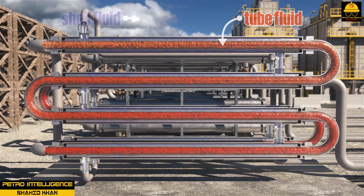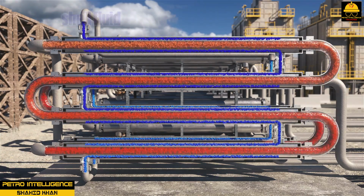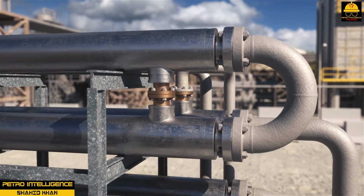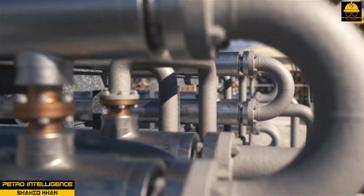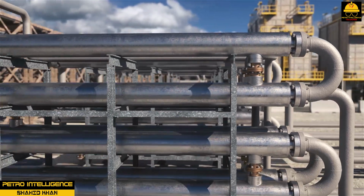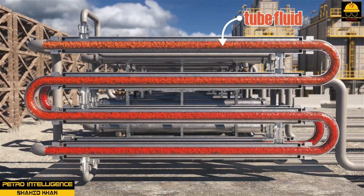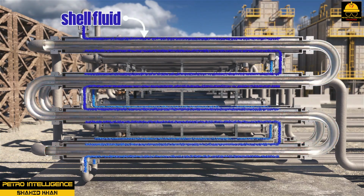This efficiency comes from the turbulent, against the grain, stripping effect of the opposing currents. Even though the two liquid streams never come into physical contact with each other, the two heat energy streams, cold and hot, do encounter each other. Energy-laced, convective currents mix within each pipe, distributing the heat. In a parallel flow exchanger, the exit temperature of one fluid can only approach the exit temperature of the other fluid.